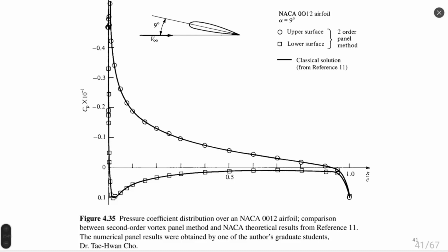And probably you remember that in the book we have a topic: is there a lift without friction? And as a result, Anderson says that, of course, if there is no friction, there is no lift. But how do we obtain lift if we do not have friction inside this model? The answer is that our model is already an approximation, it's not a real process. Our model is a mathematical way to explain physical things, it does not correspond exactly to a real flow. So this is why we can obtain lift without calculating friction.